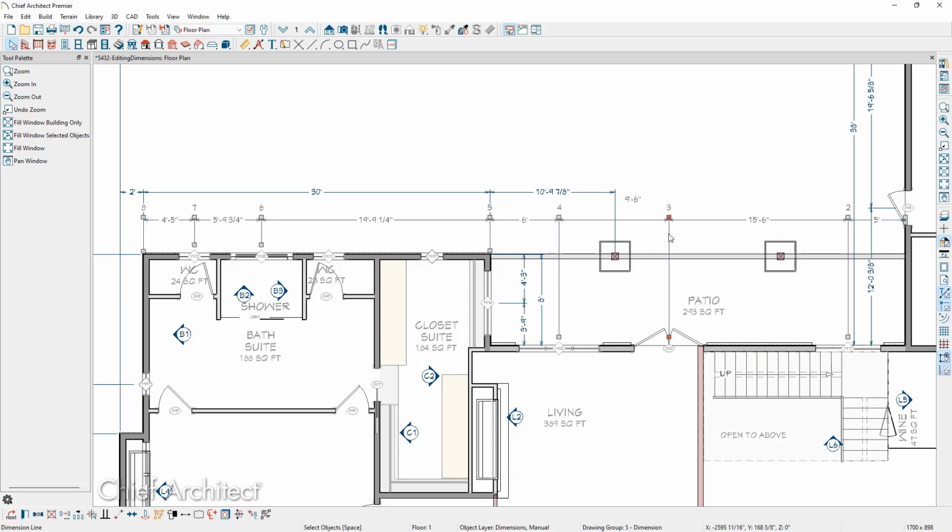If we click on an extension line, we get Square Extension Resize handles. These can be used to lengthen or shorten the extension line. The extension line we clicked on also has red edit handles. This is to indicate that this extension is our selected extension. We can mark our selected extension as a center line by using the tool for Mark as Center Line on the Edit toolbar.